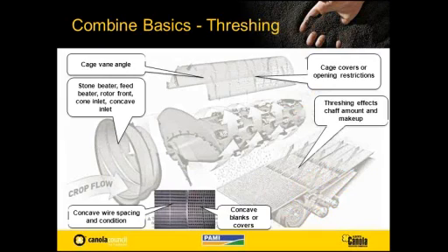Now, there are several things in there that control the threshing besides just the rotor. Some of the things you'd see is right at the stone beater and front of the rotor and that inlet. A lot of threshing action takes place there just on initial contact. So the speed, again, affects that. But we want to make sure that it flows smoothly and doesn't over-thresh there.